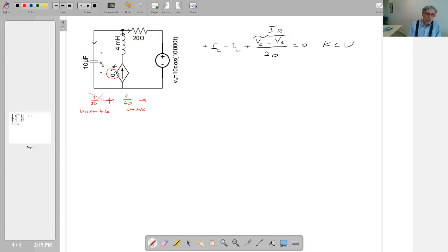So if you remember, the impedance of the capacitor was 1/(j omega C). 1/omega is 10 to the power 4, and C is 10 microfarad. So this is minus 6, isn't it? So this is going to be minus 5 minus 1, so 10 goes up, 10/j is the impedance of the capacitor.